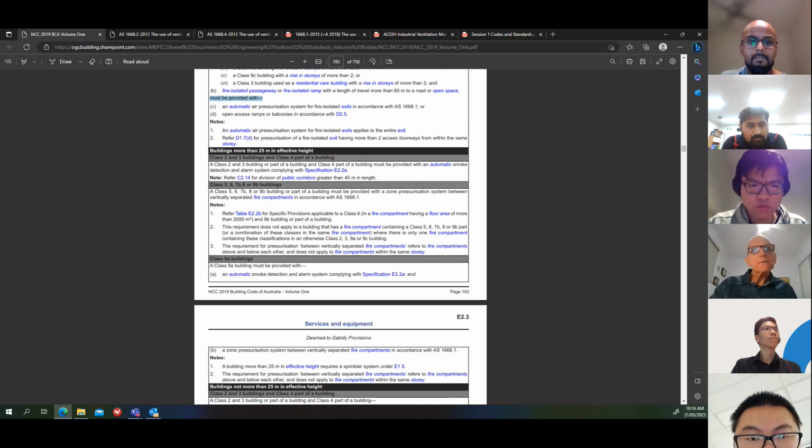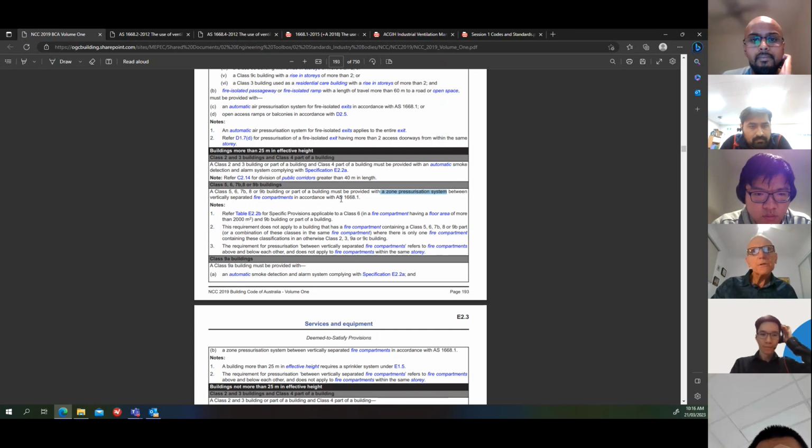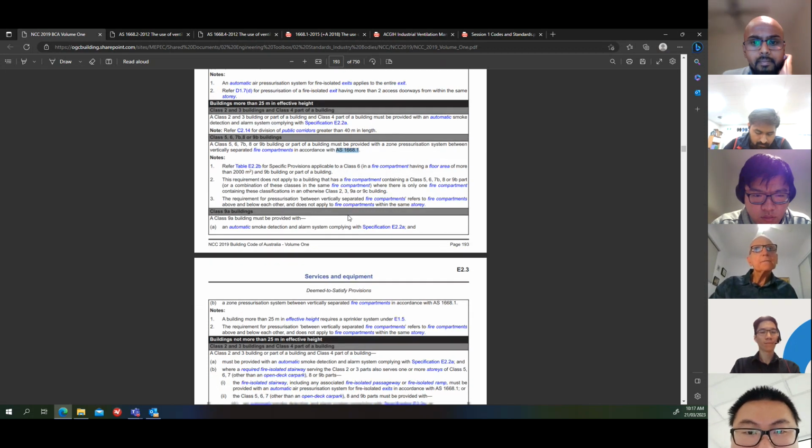Class 5, 6, 7B, 8 or 9B buildings must be provided with a zone pressurisation system. Okay? Now that's, again, referred to in AS1668 Part 1. So this is telling you what is required, but you have to go to AS1668 Part 1 to determine the details because that standard goes into all the details of how you design that system, how it's supposed to operate and be commissioned. And so on. Class 9A,